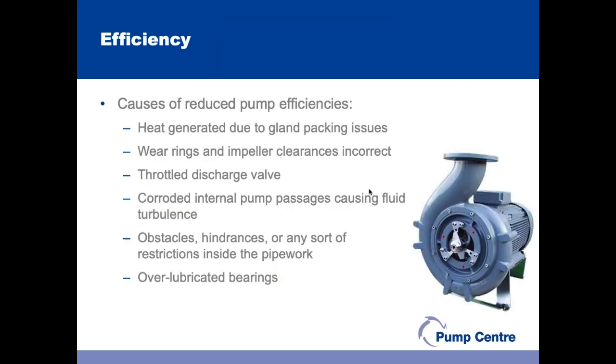If we look at efficiency in a bit more detail, there are a number of reasons why pumps may start to lose their efficiency over time. If a pump is fitted with packed gland seals, then if they're not correctly set up, you can get heat generated, and obviously that heat comes from somewhere.